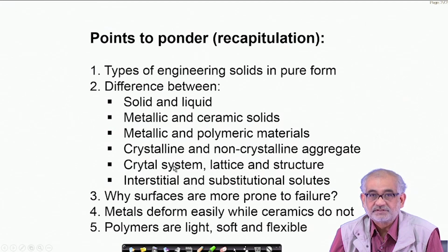We discussed nuances of point lattices, then unit cells, lattice parameters, crystal lattices or Bravais lattices, 14 of them, and then the infinite number of crystal structures that can eventually arise out of these. But we must not forget that no matter how complex a crystal structure is, if it is crystalline, then it must be related to one of those 14 Bravais lattices.